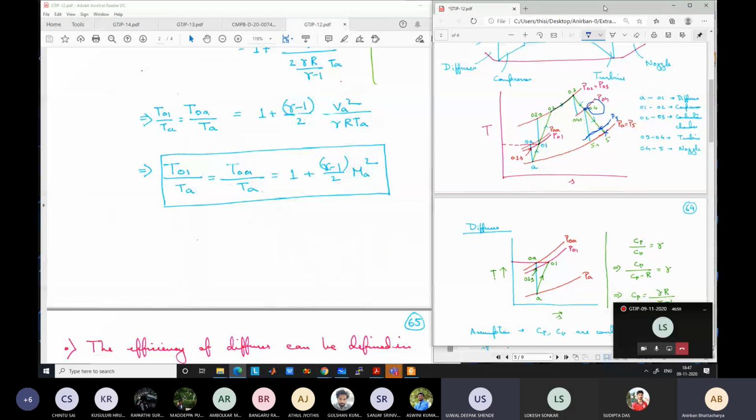But Sir, what you said, that the nozzle is unchoked, so pressure should be PA only, right? No, the nozzle is choked. We are discussing the choked nozzle now. The unchoked condition we discussed a long time back. So all this that Suman or someone was telling, root over gamma R T star, these are all for the choked condition.